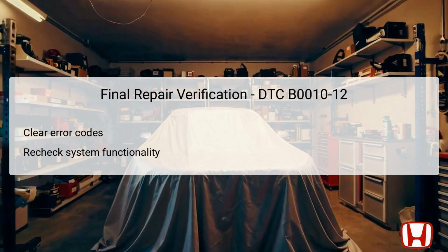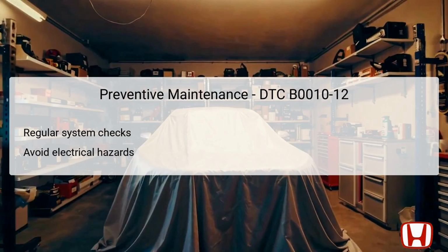case of a collision. To maintain the integrity of the SRS and prevent issues like DTC B0010-12, regular system checks are paramount. Inspect connections and wiring periodically to identify any signs of wear, corrosion, or damage that could lead to future malfunctions. Additionally, be vigilant about avoiding potential electrical hazards when working on the vehicle, such as ensuring that the battery is disconnected during inspections and repairs.